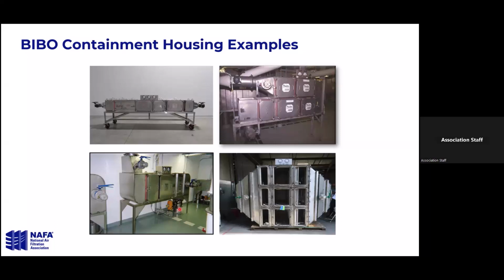When you get into the electric and pneumatic, you can get into fail-safe options where it's either fail-safe open, fail-safe close, or double acting. That way, if there's a specific event, if you lose power, you can make it to where the damper automatically closes on a loss of power. So there's some different variations depending on what the customer needs when it comes to dampers and the actuation of those dampers.